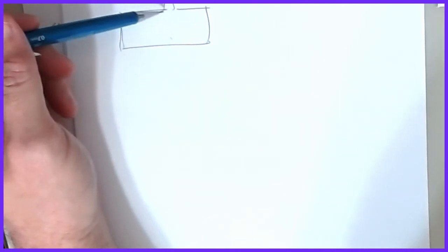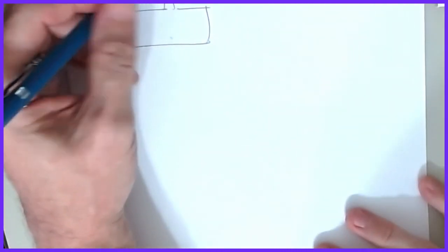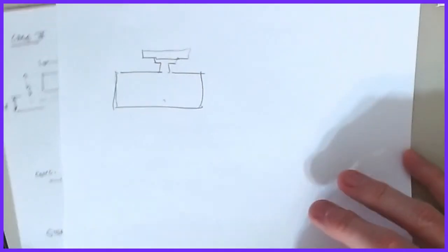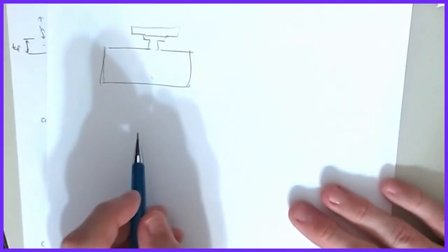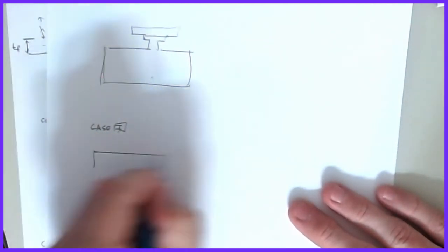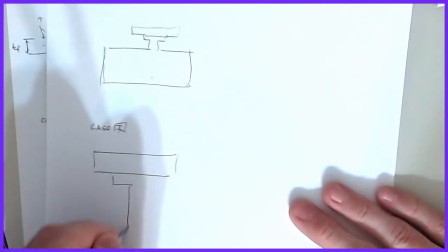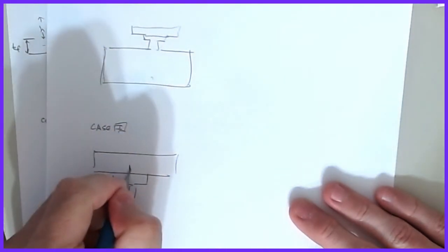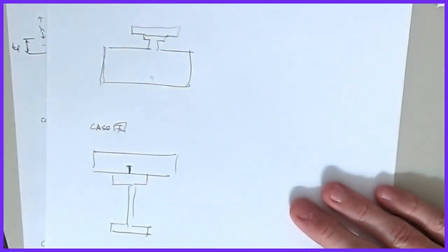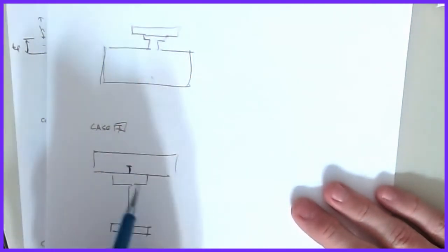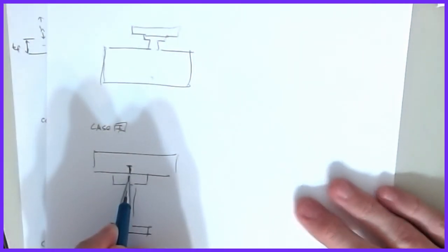I guess the hardest part about composite construction, and the thing that we haven't really talked a lot about, is the whole reason that we're doing all of this. If I go back to case 1, which was the slab, everything was up here, the one thing that we haven't talked about is that there has to be some sort of connection between those two guys, which is the headed studs or welded bars. And so we have to be able to design these. The reason we have to go through all of this is I have to know the force that acts at that interface.